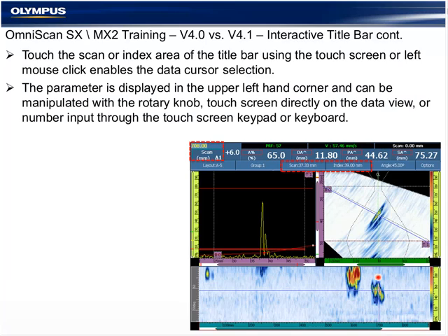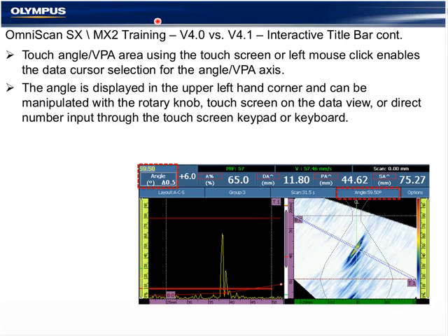The options that are available are for the grid of the A-scan and the weld overlay, and if you notice, the weld overlay has now changed. It went from a fairly bold, orange, heavy-weighted display, which in some cases obscured data, to the same black and white line as the B0 and T0 display lines. So it's much more efficient, easier for analysis, and the result of customer feedback.